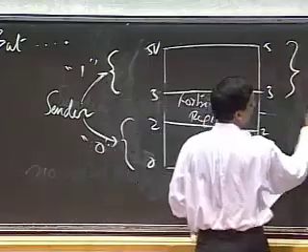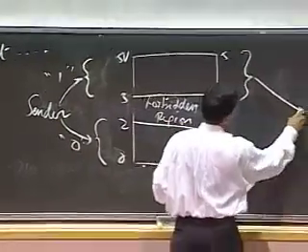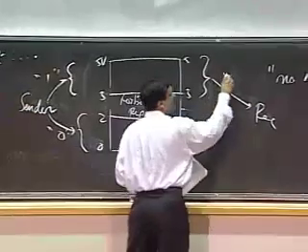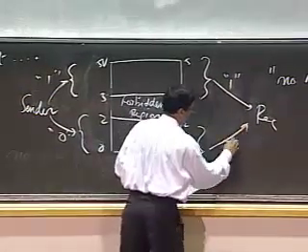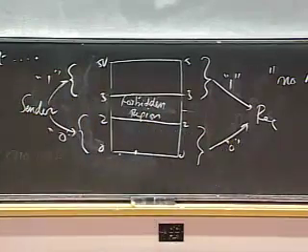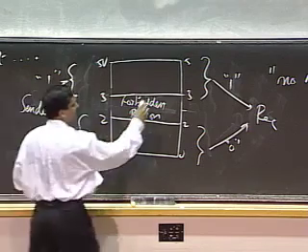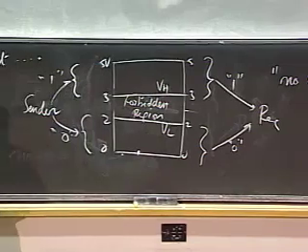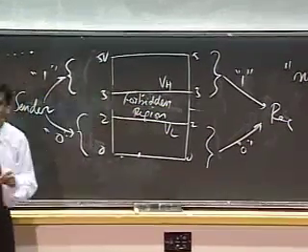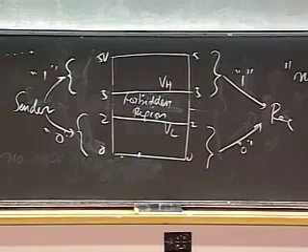At the receiving side, if I see any value between 3 and 5, I read that as a 1, and any value between 0 and 2, I read that as a 0. I may label this threshold VH and this threshold VL. So there's a high threshold and a low threshold. So this solves one problem.